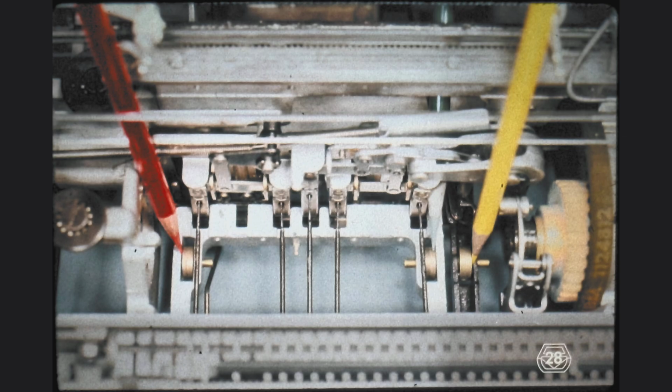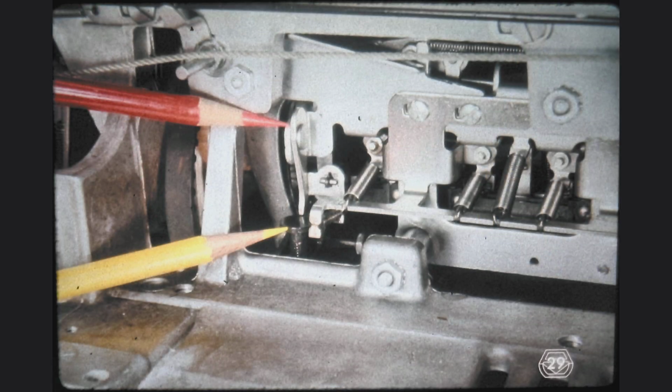For the -5 bail, however, indicated by the yellow pencil, the operation is quite different. In the case of the -5 mechanism, we have a negatively powered output mechanism. The latch, red pencil, which is pulled toward the front of the machine, releases or gets out of the way of the cam follower, yellow pencil, in order to allow the selected operation to take place. We say in this case that the machine uses positive logic because we pull forward a given latch in order to operate the mechanism to which that latch belongs.